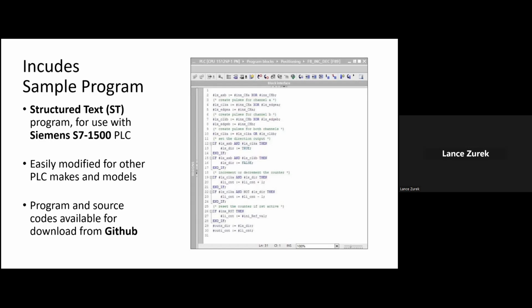Now, as with the first of the 24-volt models that we looked at today, each of the workstations of the 24-volt variation of the Training Factory Industry 4.0 model have a relay board for motor polarity reversal in both the multi-pin connector, again, 34 pins with a grid of 2.54 millimeters, along with PCB terminals with pushing connections for all inputs and outputs.